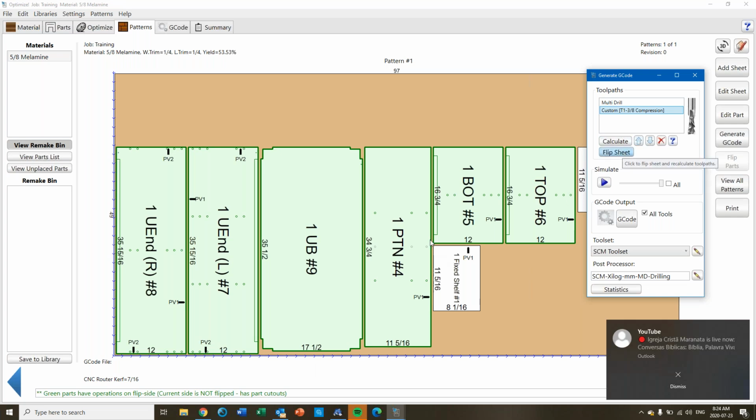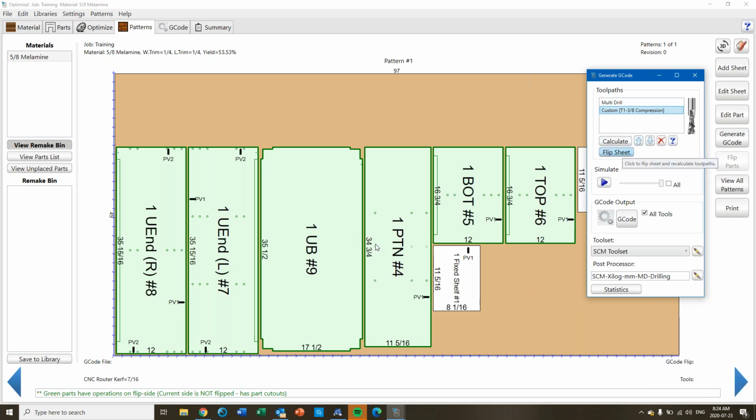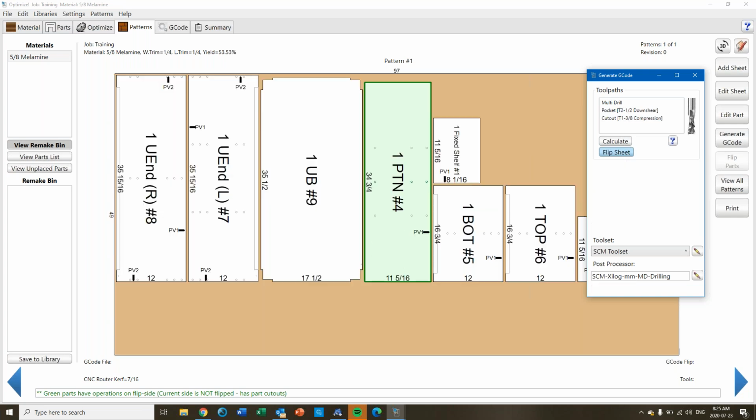So we're seeing all these parts, but we have a sheet of material with just 1, 2, 3 holes and a kind of square edge here, but we can't tell that it did that. So we really only see 3 holes. Then we're going to take this sheet and physically flip it over and put it against the pins again. And then it's going to do the rest of the holes. And then it's going to do the dados. And then it's going to cut the parts out.